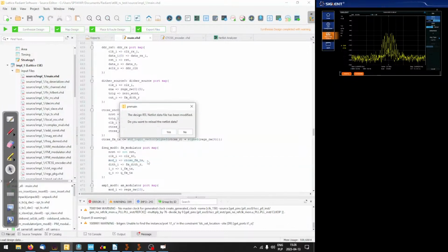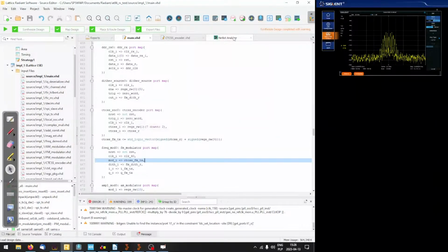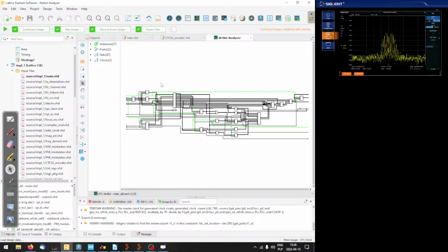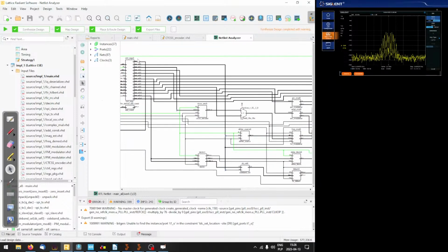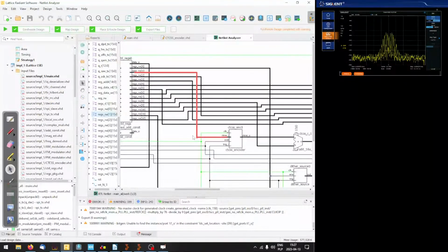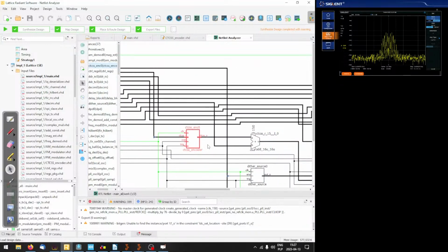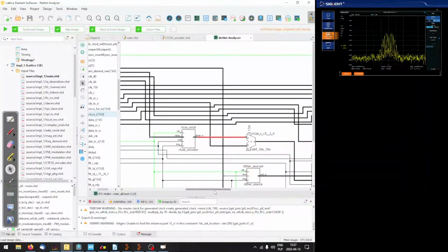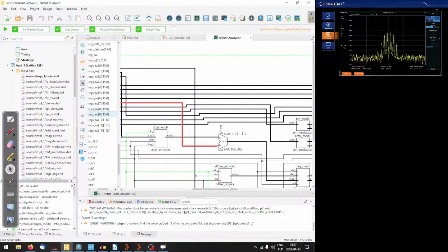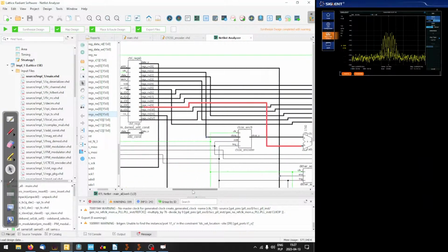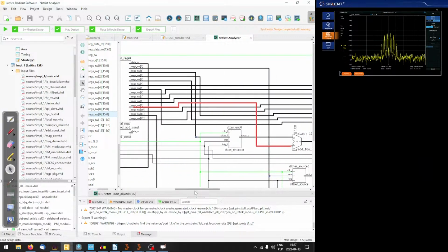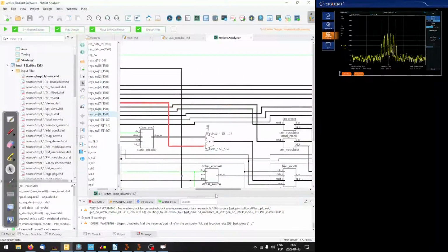All right, almost done. Yes, we are going to regenerate the netlist data, and we are going to inspect it because it's very wise to do so. So we've got register 1, then part of that register, allegedly 6 bits, gets fed to the CTCSS encoder, and the output from that gets combined with the value held in register 9, the signed value, 16 bits.